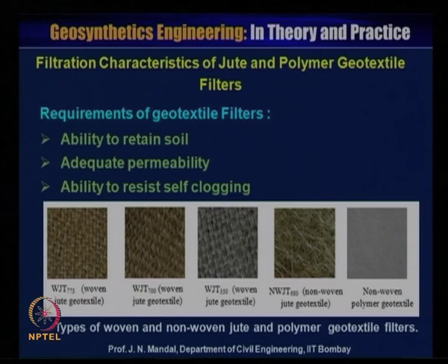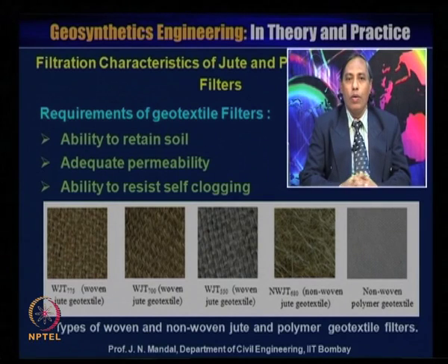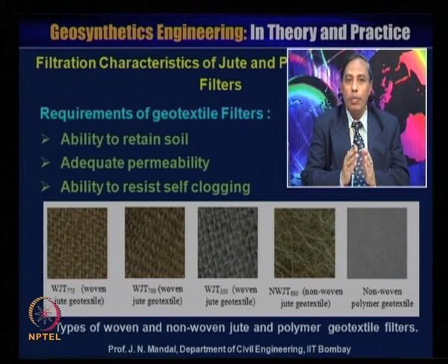The most important requirement of a geotextile filter is the ability to retain the soil, adequate permeability and ability to resist self clogging. These are very important parameters for the filtration and drainage for any kind of material.